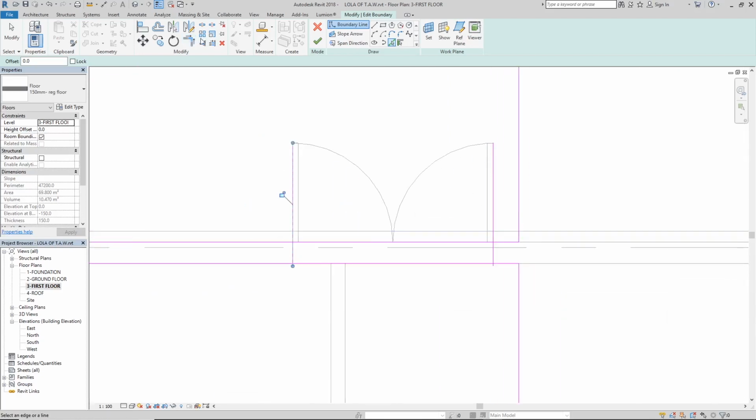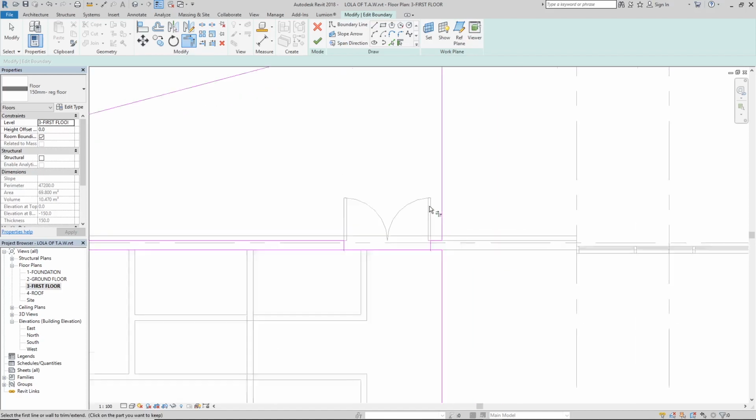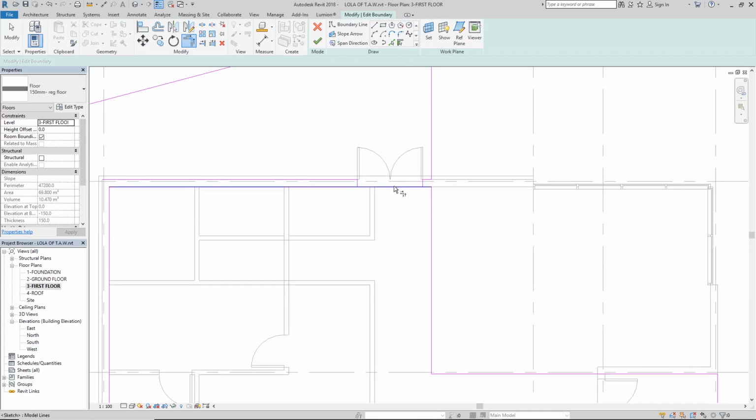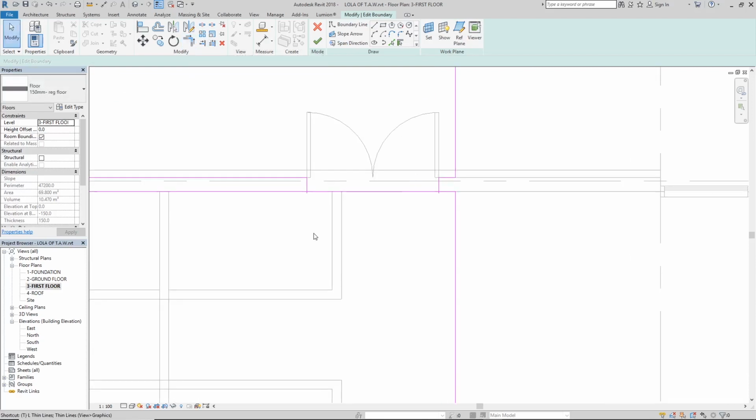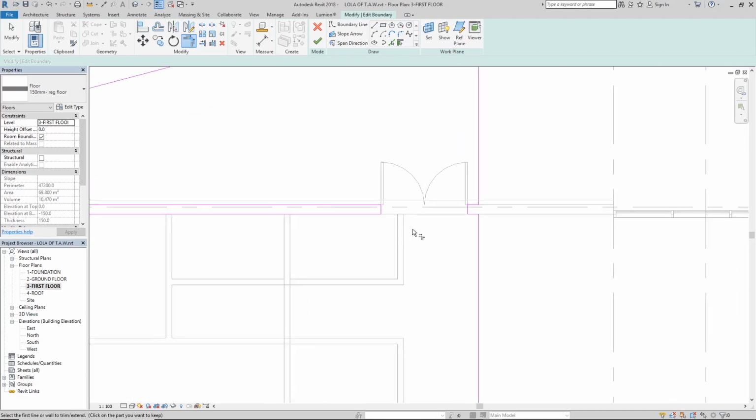So what you're going to do now is you're going to click your trim and extend tool, and then you're going to pick this line and you're done. This line and this line, and you're done. So you're going to repeat a similar thing for this line. Click escape, go to your split element tool, split this line, escape, trim and extend tool or TR. Click this line and this line, this line and this line, and then you're done.